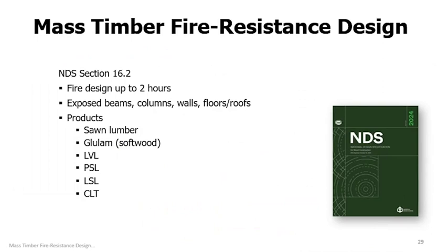Chapter 16 of the NDS allows the fire design of exposed wood members for fire resistance ratings up to 2 hours. So the limit is 2 hours for exposed wood members. We'll talk about protected wood members also in a little bit.